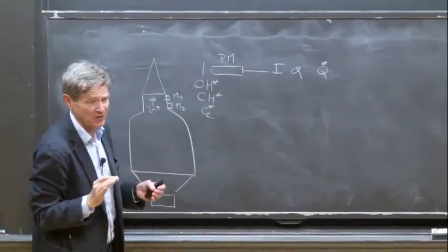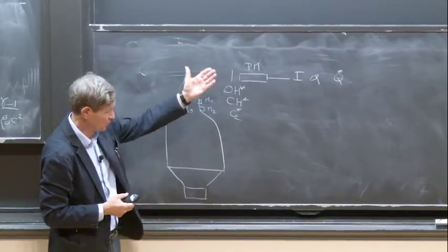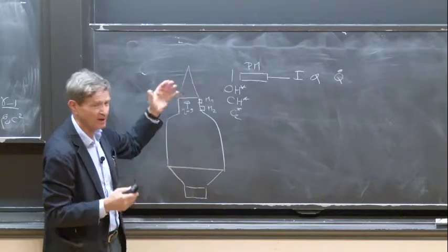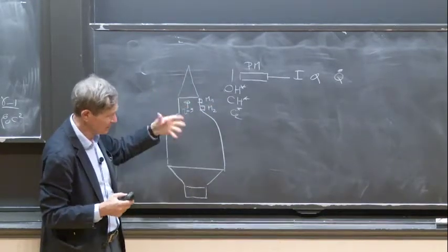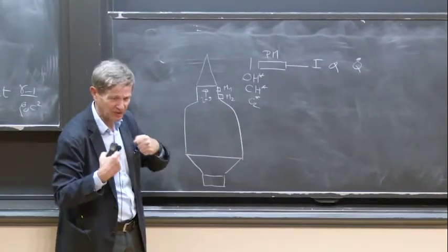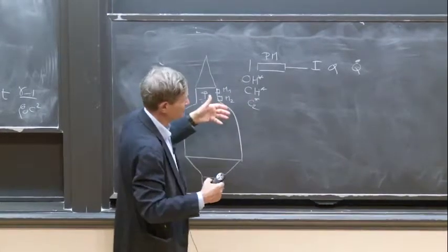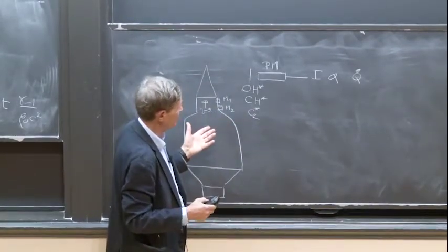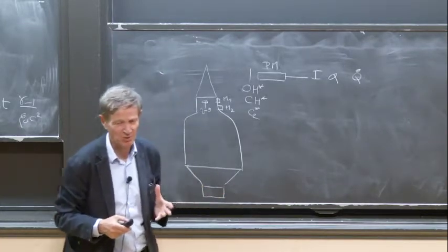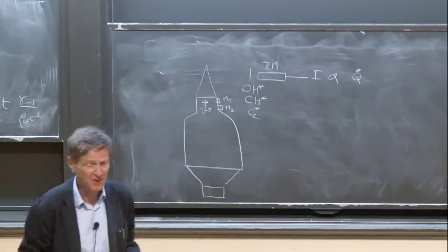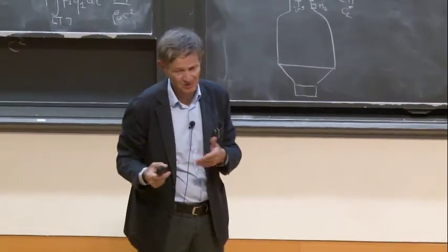It's not perfect. You can try to look at this relation at a given equivalence ratio, and you find out that definitely there is a relation. When the flame radiates in these bands, there is a strong heat release. When the flame doesn't radiate, there is little heat release. This is good for premixed flames. We don't have something like that for non-premixed flames, but much of the interest now is in premixed flames.